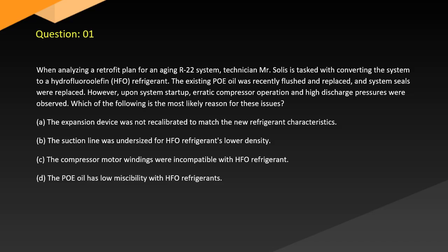A. The expansion device was not recalibrated to match the new refrigerant characteristics. B. The suction line was undersized due to HFO refrigerant's lower density. C. The compressor motor windings were incompatible with HFO refrigerant. D. The POE has low miscibility with HFO refrigerants.